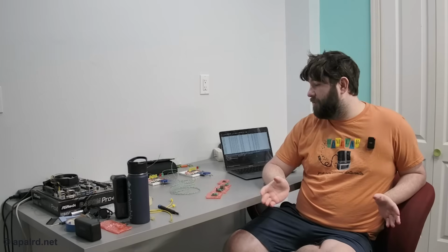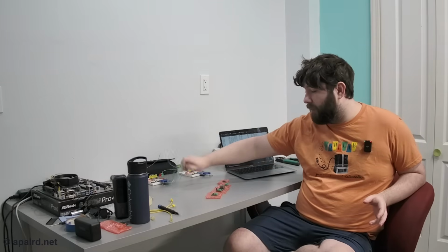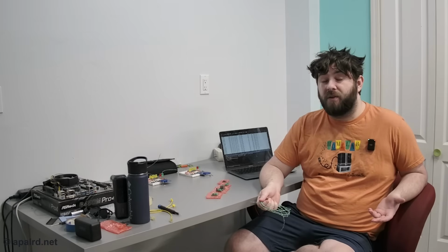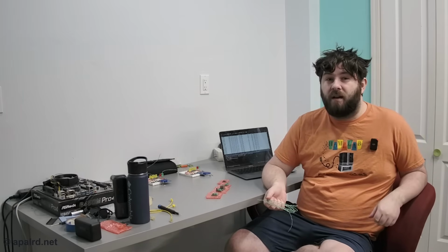So one of the big drivers for this whole single pair Ethernet in the automotive industry is going from a function-based network to a zone-based network. I worked in automotive before. We had 2 CAN buses on the cars back at the time, 10 years ago. The body CAN, the chassis CAN. On the body CAN, we have modules like self-leveling headlights, powered sliding doors, powered lift gates, the radio. Those are all speaking to the body because they're things the occupants and interiors deal with.